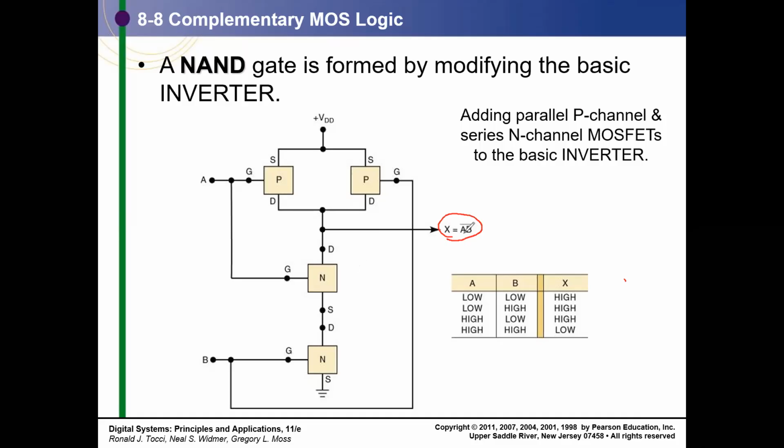Since A and B are a dot product, the transistors corresponding to input A and input B are in series. So you connect the two transistors in series and the network is realized. For P, you have to make a dual network. Dual network would mean the transistors in series will become parallel, and those in parallel will become series. So here the two transistors were in series, now they will become parallel.